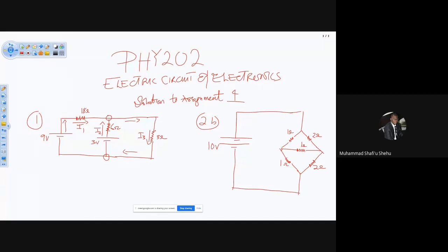So now we're going to choose the bigger power source, and take the loop direction for both based on it. Look at the bigger power source. It's 9 volts and it's going upward. So the loop is definitely going to be clockwise in both, right? Right. Good.